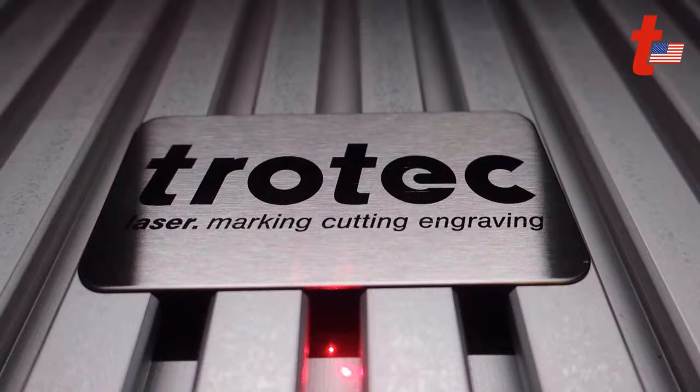Just note that it is 2 to 3 times more time consuming than engraving depth into the metal, or a slight amount of depth, or just engraving into the metal, because it takes so much higher DPI since you're drawing heat out. Different levels of stainless steel that have different levels of carbon in them will affect how long this takes. Different types, your 302 and your 304 stainless, will effectively take different times to produce the annealing effect.